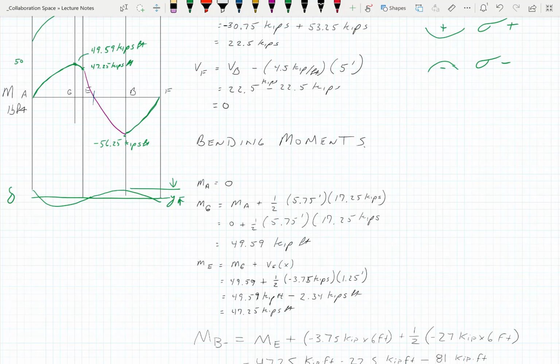Can I borrow you from that? Just read that so everybody can see it. All right. So as we bend, this top side is in tension, okay? This bottom side is in compression. We're squeezing the metal fibers back together in the bottom while we're stretching them out at the top. Okay? But the neutral axis bit that I talked about has got no stress on it. So the bigger the beam, the more tension there is on top, and the less here.